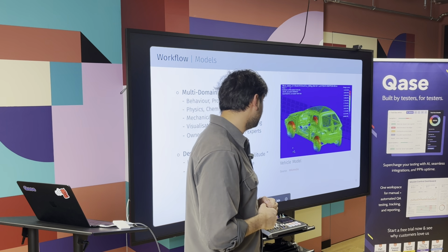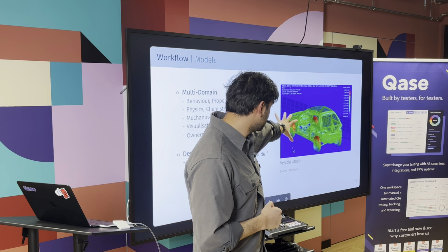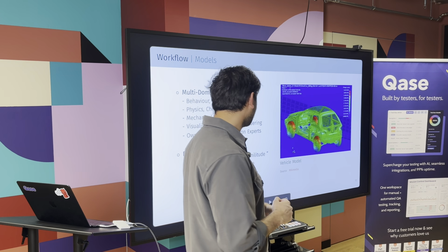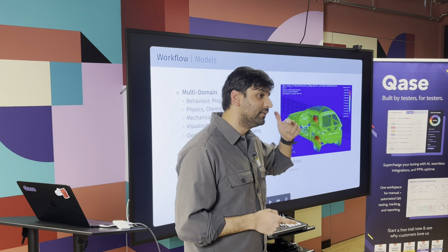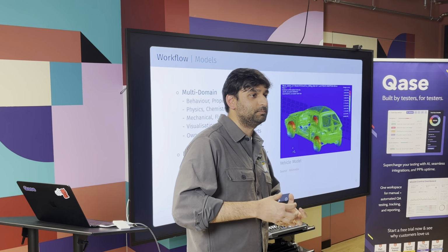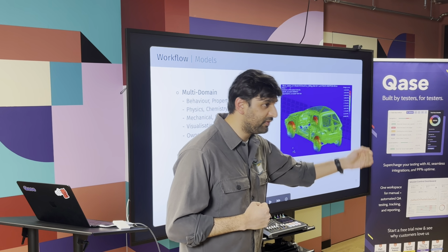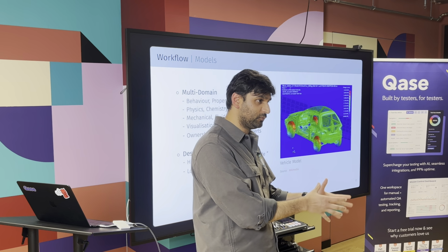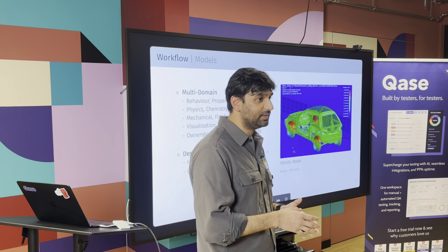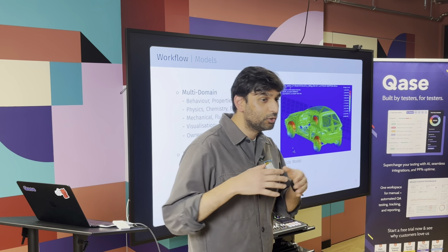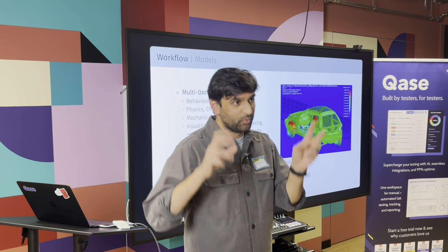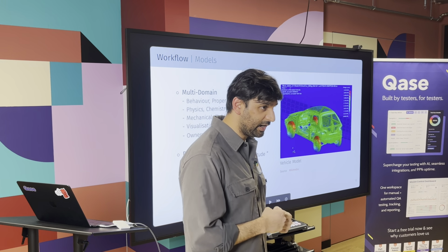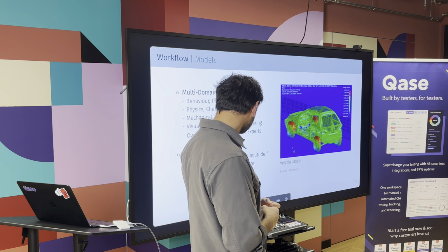You know, when people think of a model, they think of a 3D or 2D visualization. And that's part of it, but the model isn't really just human facing. It has to be facing your device under test. The control software that is being tested must think it is connected to the real car, not some digital twin of the car. It is connected to the digital twin, but it must believe that it's in the real car. And that's what you want to simulate, right?